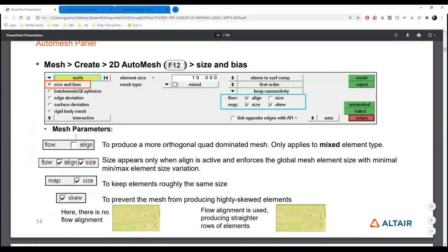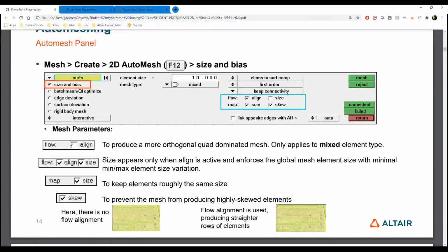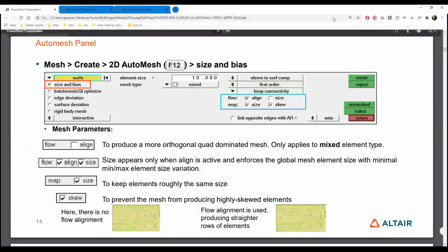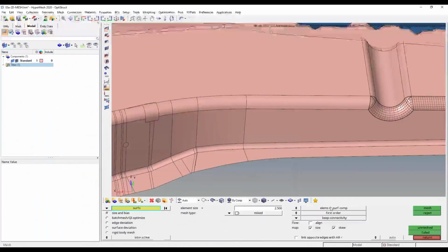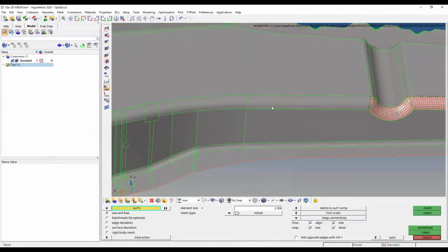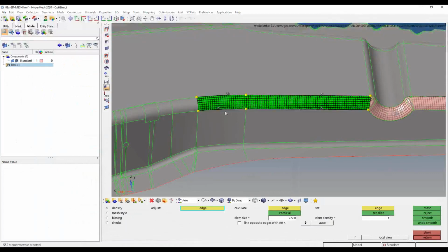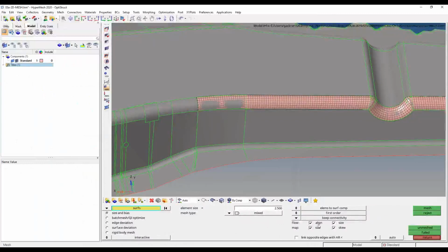And knowing that a lot of these controls are designed this way gives you confidence even at a beginner level. When in doubt, you can just turn on your mesh tool and check all 4 of those boxes. Now I'm pretty confident that whatever it yields, if I don't want to make these incremental decisions, these 4 in parallel are making those tough choices for you. As you get more experience and a little more picky, with more specialized requirements for your meshes, that's when you can start turning those off again and reintroduce some more manual effort.